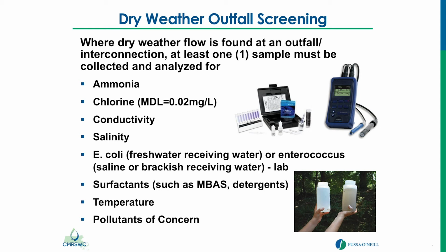So that dictates how many samples you can get to in a day. You're not going to be able to do 20, 30 samples in a day, because you only have 6 hours from the first sample you take to get all your samples that day to the laboratory. So it does take some pre-planning on your part when you're going out and doing this sampling.